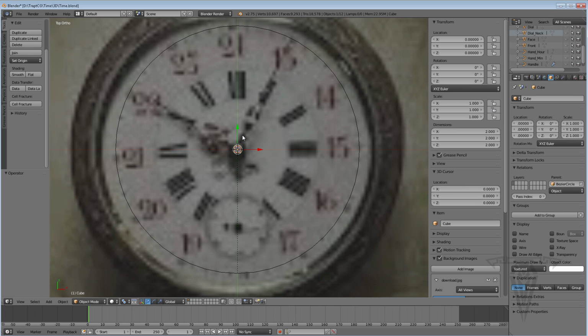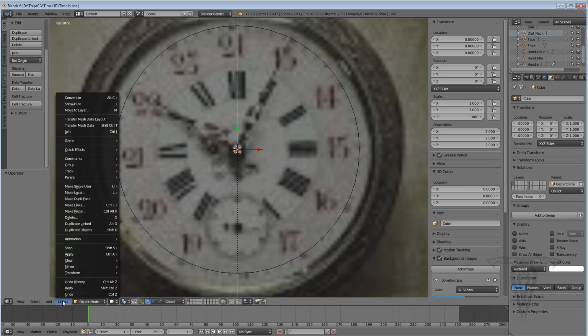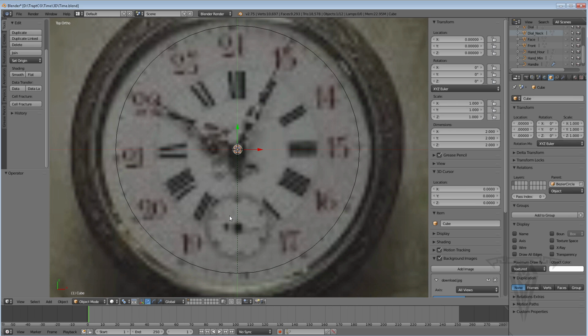So let's select the box. Now I want to reset this guy's center point to be along the path. To do that, again, object, and it's clear. I'm going to find the word clear right here, clear. And we want to clear the origin. So Alt-O on the keyboard, Alt-O, and now the box is along the path.